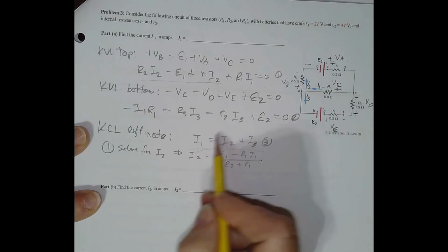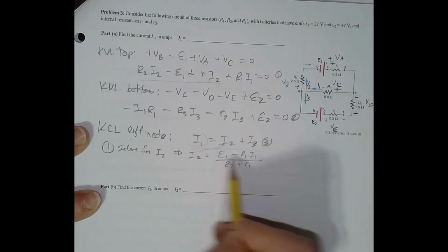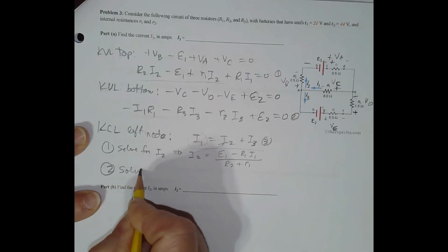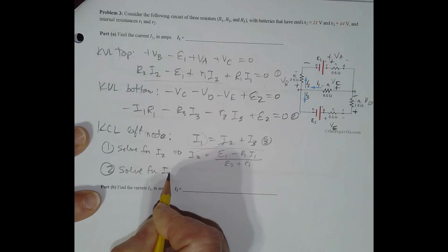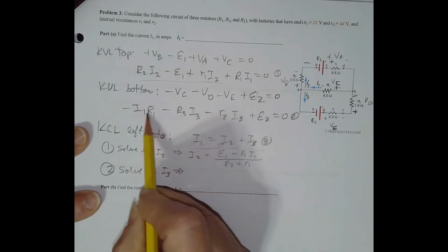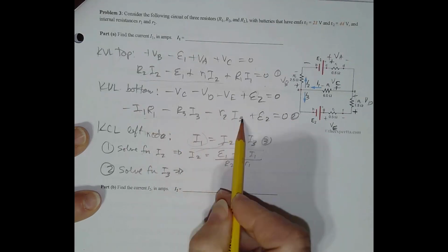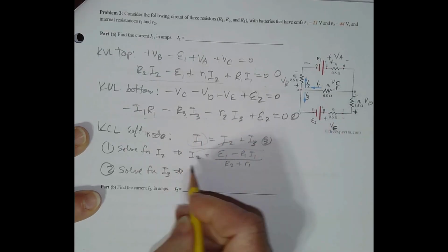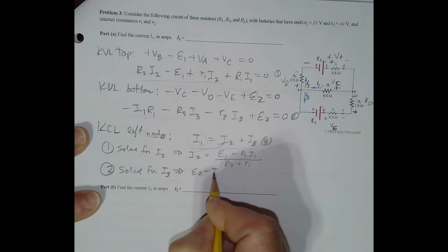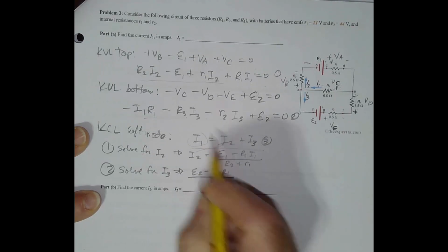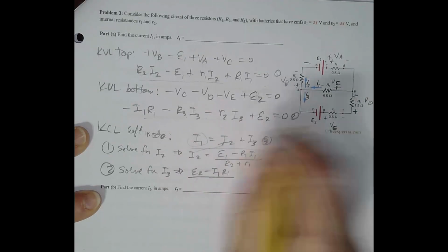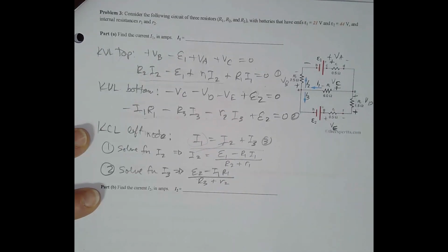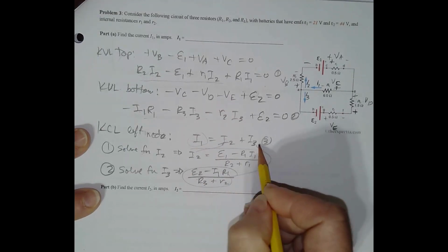So I'm going to make this last equation have only I1s in it. So we've got I1, I2 in terms of I1 will go there, and then we're going to use 2 and solve for I3, right? So we're using this one. It's got just I3 and I1. So if we're going to solve for I3, let's take it to the other side. So we're going to have E2 minus I1R1 divided by what was the coefficient of I3 on the other side, which is big R3 plus little r2. All right, so now I can take this and put it in for I3